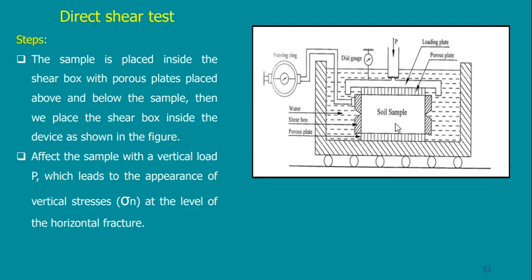But it is very good for comparison, because if I have two kinds of samples, clay and sand, and I put a sample of clay in this sampler, and I put a sample of sand, and then I get a value of C and phi for each, then the comparison will be very good, because I'm comparing apples to apples, oranges to oranges, but not comparing the result of C and phi of a material from a triaxial test with the C and phi of another material in a direct shear test. Then I'm getting different values. So this is what I want to stress in this lecture.